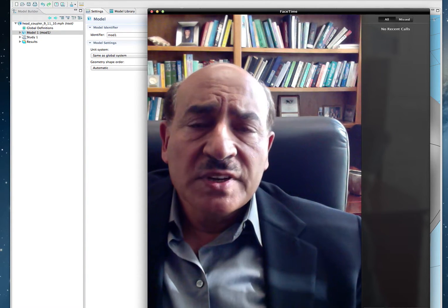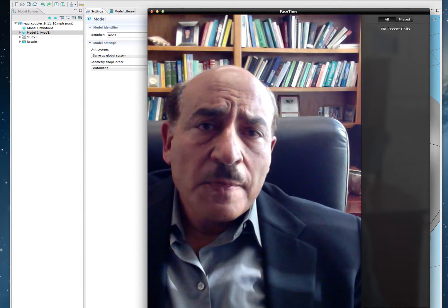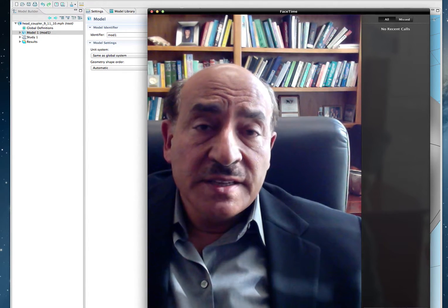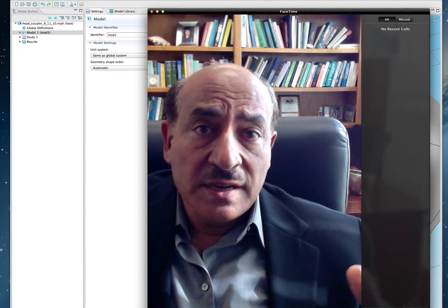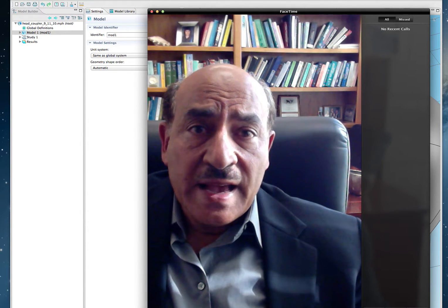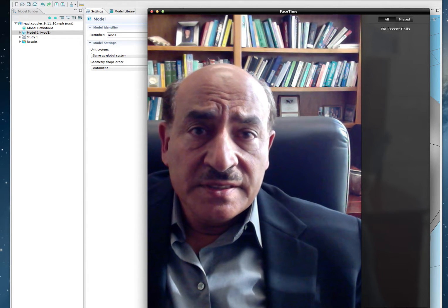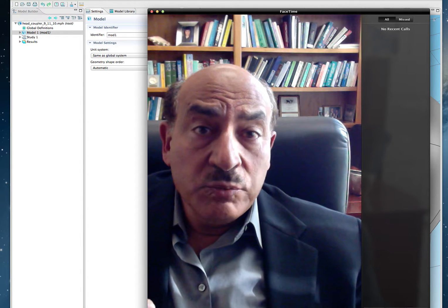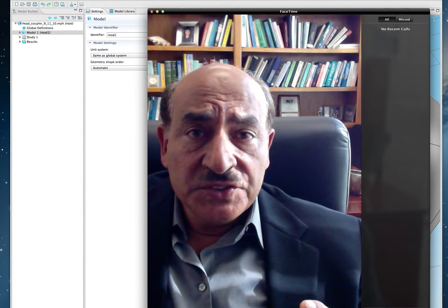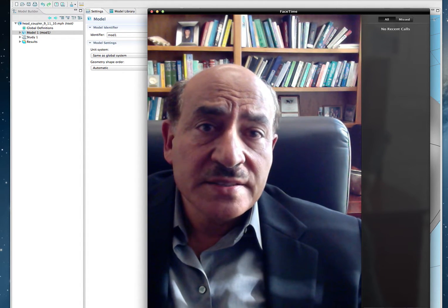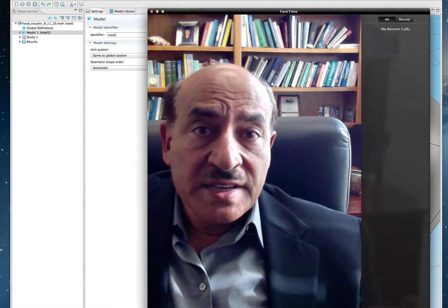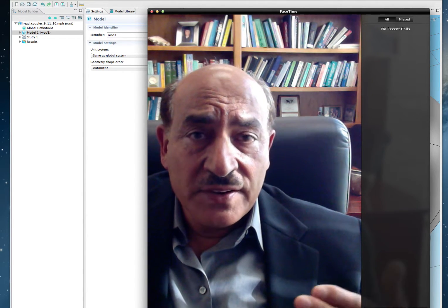So this model here that I'll describe to you is the following. I was working on a problem, and in this problem we had a tank head, so it's a very big tank, and it has a head that I had to make. It's a 3D cover, and we wanted to cut an axis hole in the top of the tank head, and then connect to it a coupler, and then do welding to the coupler. So the problem was to do a transient heat transfer during the welding process, and then to recover the residual thermal stresses as the material is cooling down.